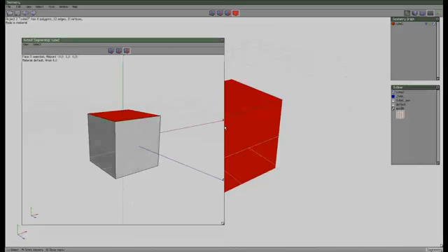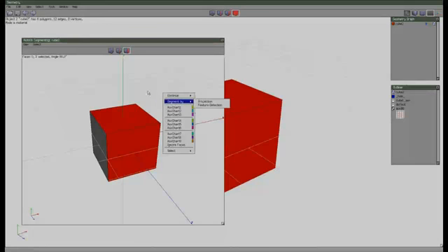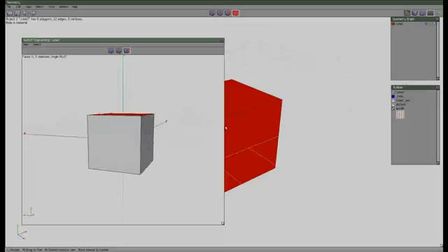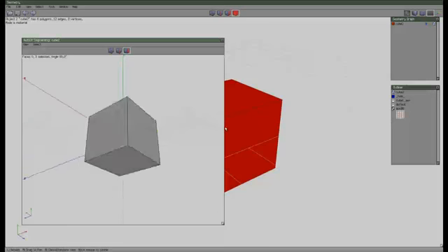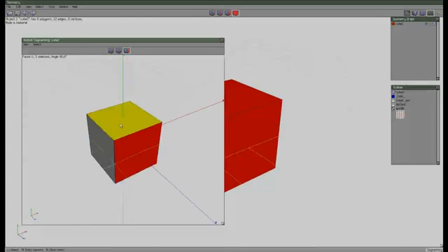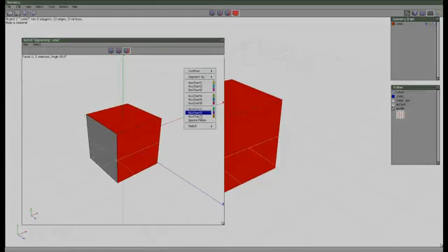Now, I should probably explain a little bit how Wings does this. It's a little bit different. It's not really a traditional way of unwrapping. It's actually pretty cool. When you make a selection, so for example, let's say I want to unwrap this cube, so these three faces and then this one, and then these two, I want them separate. So what I can do is make that selection. So that's one part, and that will be a second part of the unwrap, and I can make the selection and then right click and just give it one of these colors. It doesn't matter which one, just let's say chart 1.